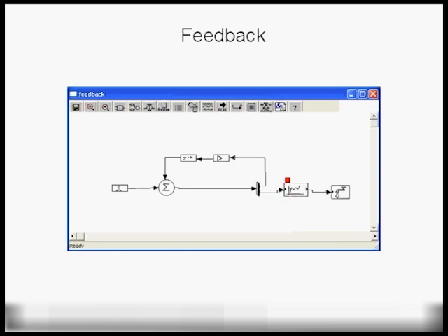The plot block is very interesting. In fact, the plot block, if you generate 1 million samples, it would just sit there and collect those samples, and at the very end of the simulation during wrap-up code, it will actually plot those results. It actually has another mode of operation in which it would plot samples on a window basis as they are generated, so you get a nice dynamic effect. But its default is to actually statically sit there and collect all its data and in wrap-up code plot the results.